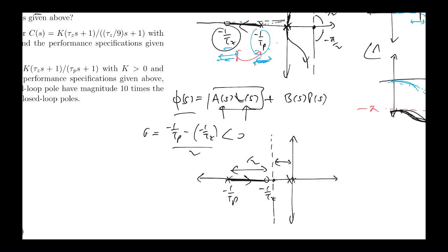Right, so we can control where these are by changing the location of the pole of the compensator. If we push the pole further that way, the asymptotes will move further that way. Right, so as we increase k, we've always got 3 poles. One of them will be here, right? The other one will be along this line going towards the asymptote at an angle of plus pi on 2. This one will be going towards the asymptote at minus pi on 2. They will always be in the left half plane.